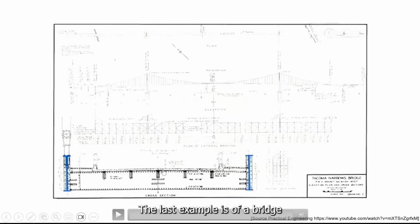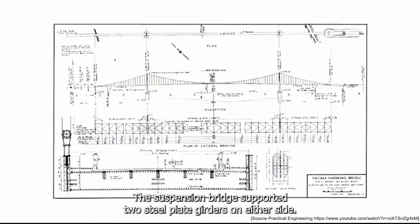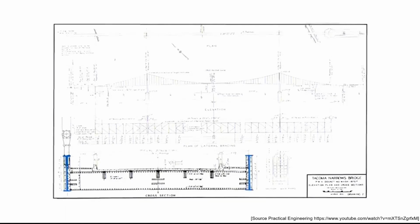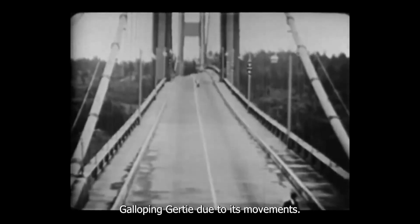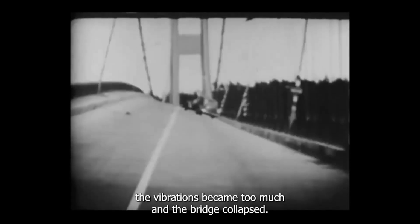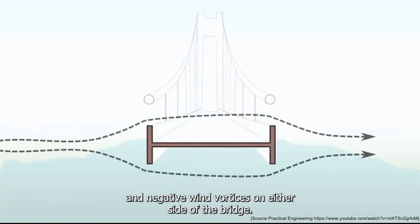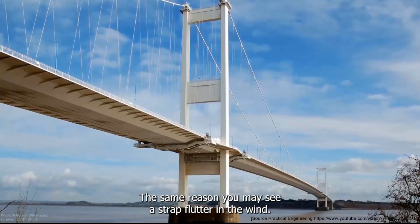The last example is of a bridge in Tacoma Narrows that was built in Washington State in 1940. The suspension bridge supported two steel plate girders on either side. The bridge was very flexible and was nicknamed Galloping Gertie due to its movements. On November 7th, on a particularly gusty day, the vibrations became too much and the bridge collapsed. The cause was aerodynamic flutter, or the action of the positive and negative wind vortices on either side of the bridge. The same reason you may see a strap flutter in the wind.